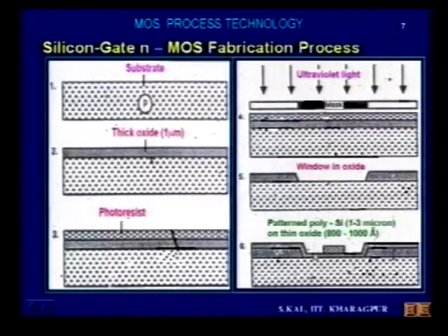So polysilicon is removed, but the oxide is there, and now through oxide you can implant source and drain, because here oxide thickness is very less, and it will protect the silicon from surface damage. High energy implantation is being done through thin oxide. The implant species can penetrate, and damages will be less at the interface, so that leakage current will be low.